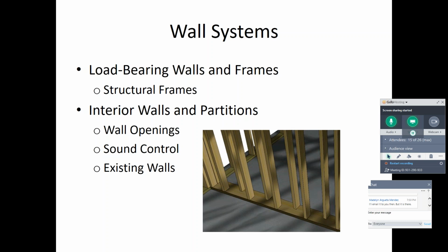So I've showed a picture on here where we have, this is fun to say, double studded staggered construction in the lower right hand corner. And it's great for sound control and load because they're staggering those 2x4s, right? We see one forward, one back, and then there it seems almost extra. Whereas usually we might just have this first row or just the back row centered. So they're staggering them left to right, forward and back.